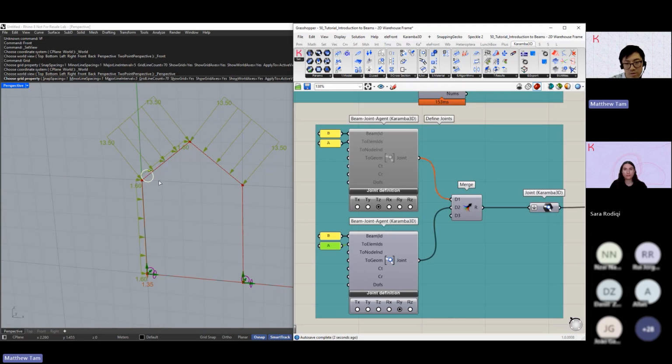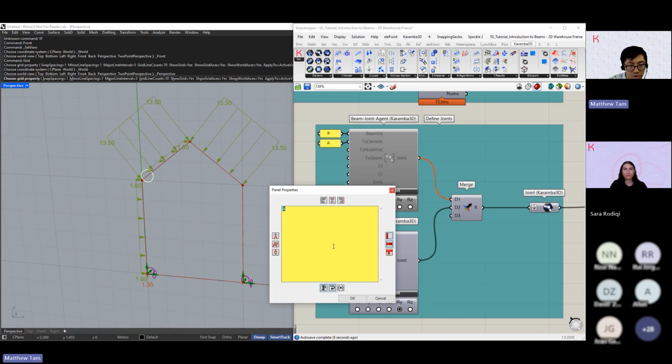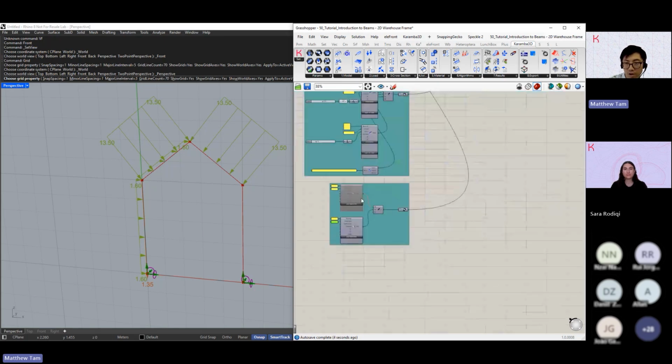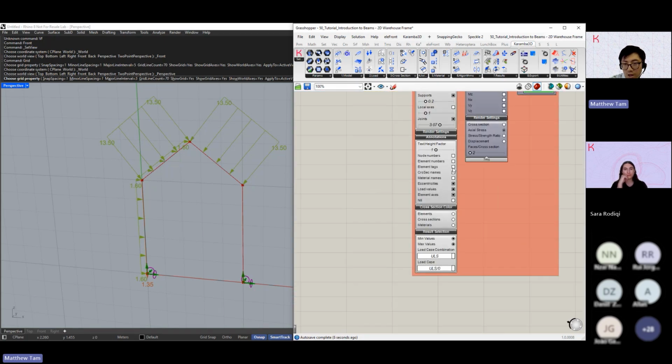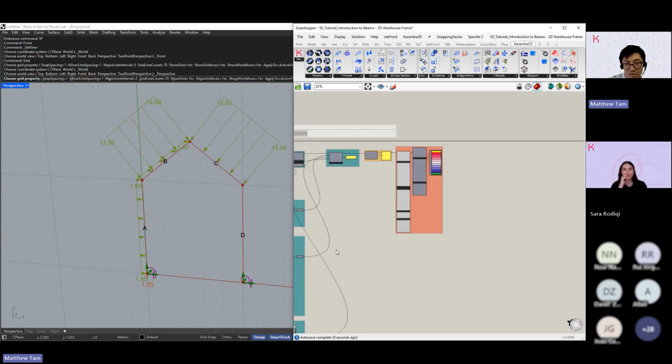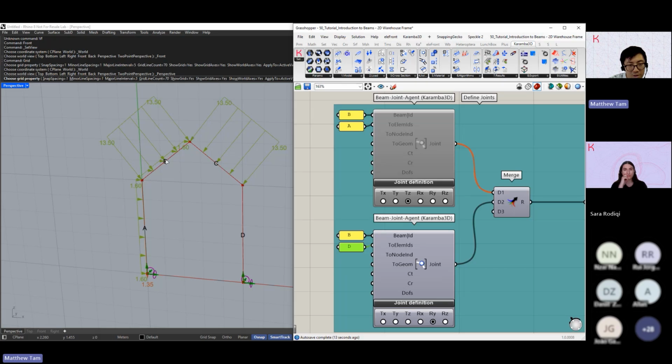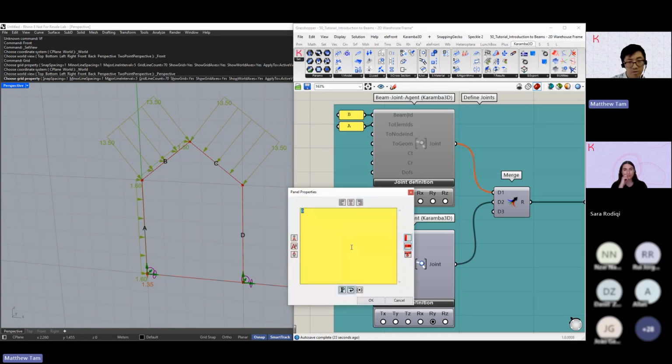So it would only, and if you were to write, for example, D, B does not actually connect to D. If I actually go to the element tags, we can see our actual element names. I should have done that before, but here you can see B element doesn't connect to D, so that's why there's no joint being applied here. So you can use it quite intelligently to give, let's say, a rule-based system for your joint conditions here.